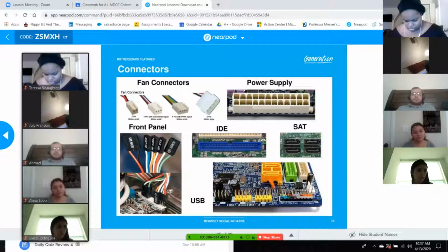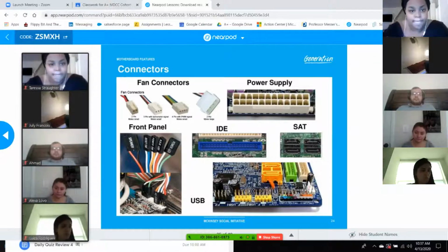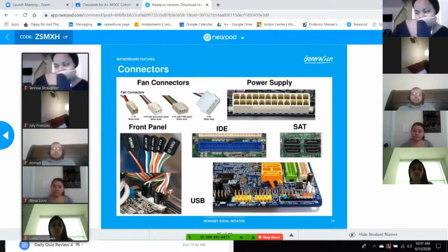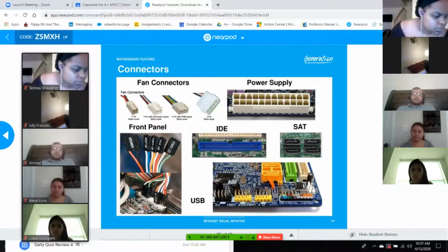Over here on the top, this is the big doohickey that comes straight from the actual power supply to the motherboard. If you notice, on purpose, since it is a perfect rectangle, there's a square, a triangle shape, a square. If I flip-flop it, you'll notice the square is not here, it's a triangle. So if by mistake I try to put this in incorrectly, it will not allow me, because each specific hole has its own little shape that must align to the connector. They do this a lot. For the most part, you need to recognize where the notch is and/or just flip it.